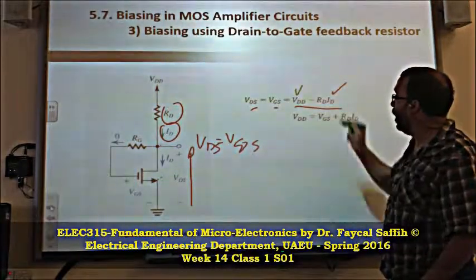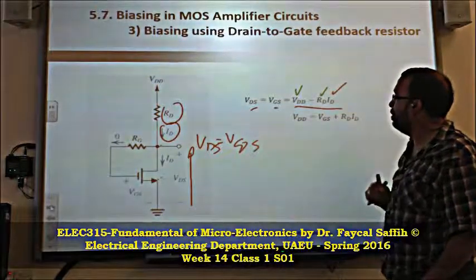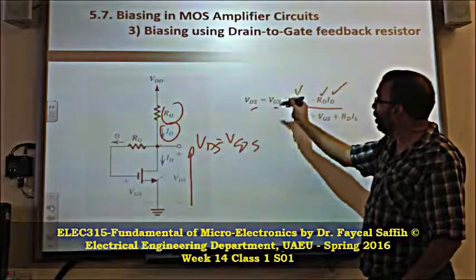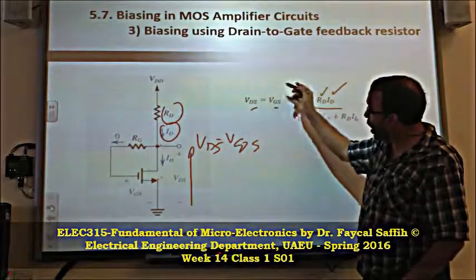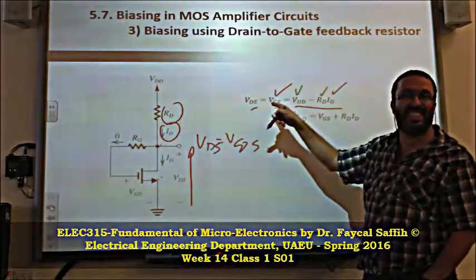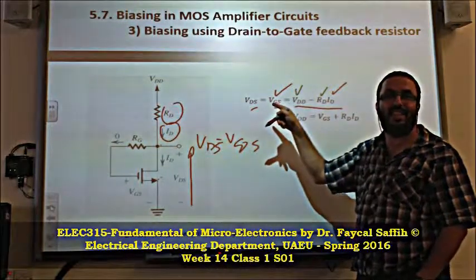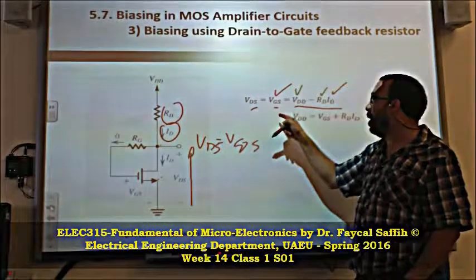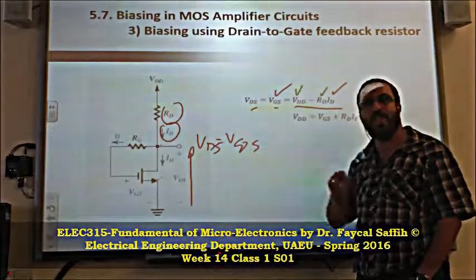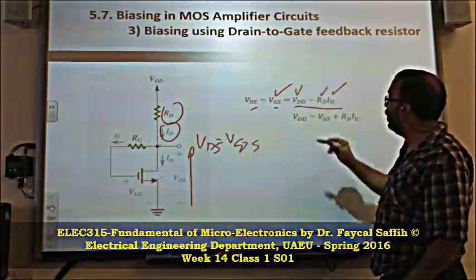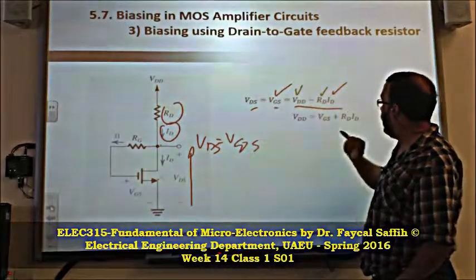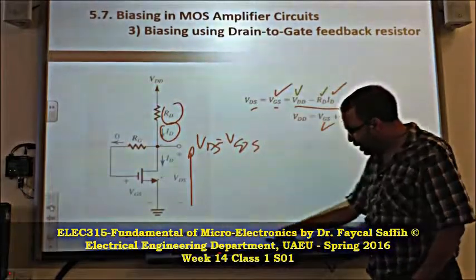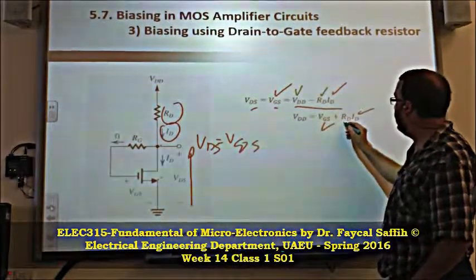Green. RD also is constant. Green. Oh, very nice. So I'll bring this constant. And also this one VGS change or no? Change, because this is the source of the change. VT is in VGS. Remember that? VT is in VGS, and that's why it makes ID not constant. It may change from device to device. So what do we do? We bring these guys on one side. So this is changing, this is which one? This is changing, and this is what? Constant. Yes.